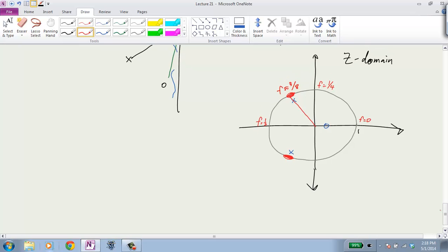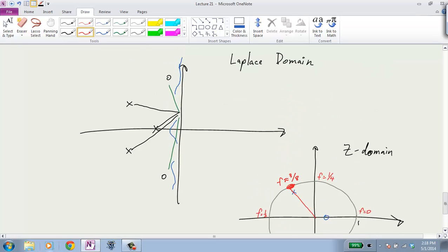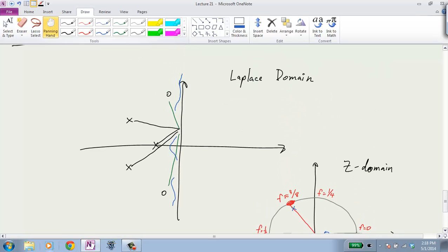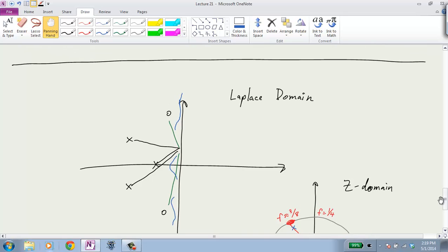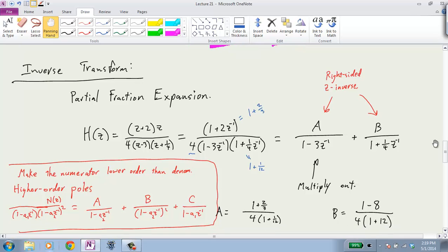So from the poles and zeros, you can learn several things. And the one other thing that we see because of partial fraction expansion, aside from getting the frequency response, is that we know something very quickly about how this behaves in time. Because when you do the expansion, all of the poles are going to get their own term. Remember, we expand a fraction into sums of terms, each with the poles of the system.